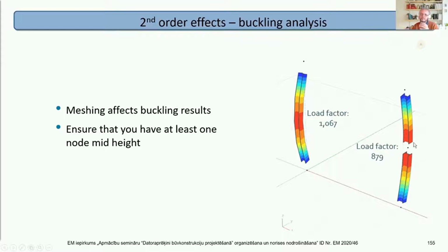Now, that's for a 1D element. A single mid-height node is usually enough. Experiment. Split it again, see if you get much difference.